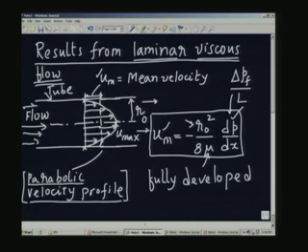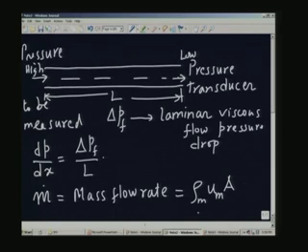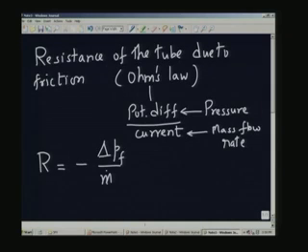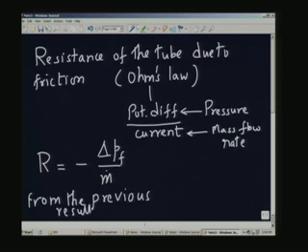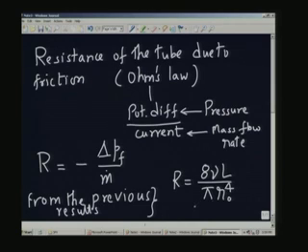So, I am going to take this expression, and the second expression I have got is rho m um into A equal to the mass flow rate. So, I am going to substitute here, and then number 3, I am going to substitute delta P f and m dot and obtain the resistance. So, I will just give the expression. From the previous results, after some simplification, we can show that R will be nothing but 8 nu L divided by pi r naught to the power of 4, where nu is equal to mu by rho m.